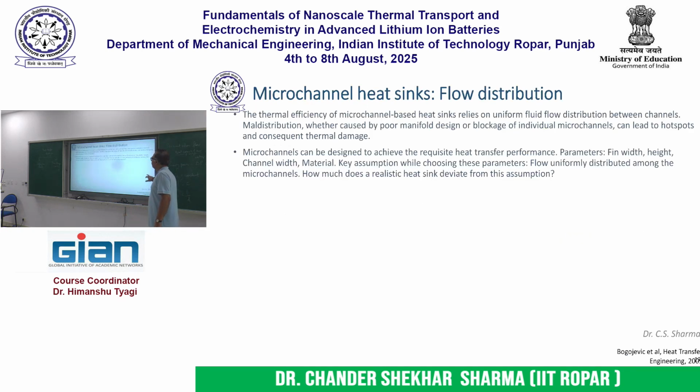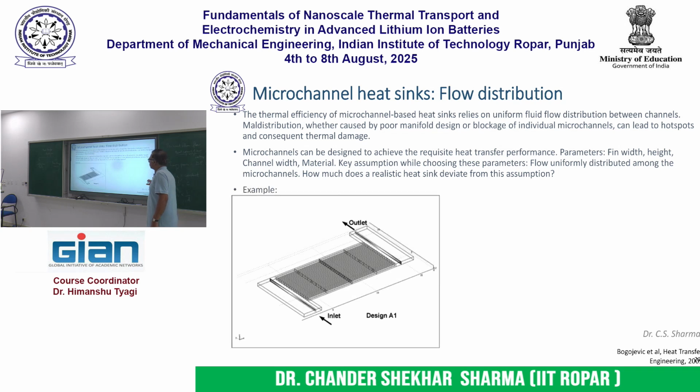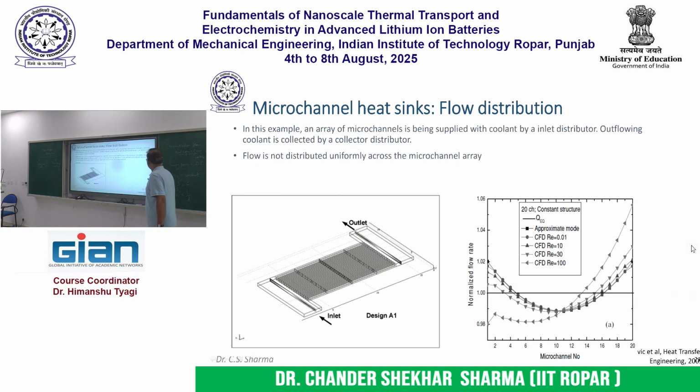So when we talk about microchannel heat sinks, overall what will be the architecture? You will have a duct that is bringing in the coolant, which is distributed through the microchannels, and then the hot fluid goes out, right. But here it brings up another technical challenge: how the flow is getting distributed in different microchannels. You would want the flow to be equally distributed, but because of the nature of flow, the flow distribution is non-uniform.